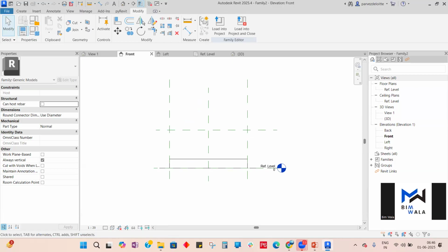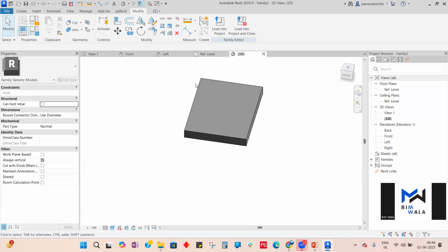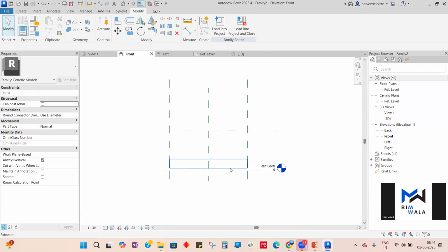Again, Revit has settings which are specific to the particular view. That means if you set shaded in 3D, that doesn't mean it will show shaded in every view. You need to go to each and every view and change the view settings. Does that make sense?